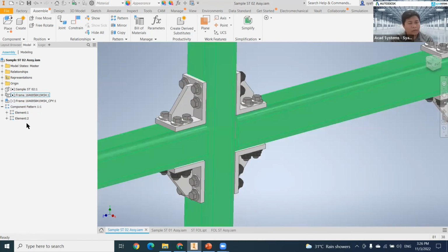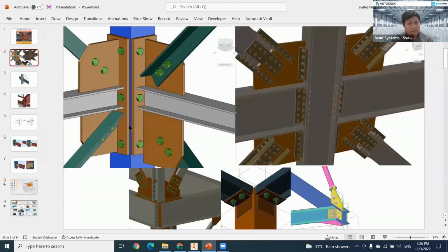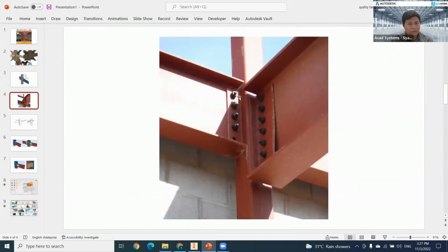If you go back to our sample here, what you can do is this: if I plan to create this kind of joining, no problem. I just need to create a plate. Make sure that all these items are trimmed with a distance for the thickness here, and then create a plate and directly do the bolt connection over here. Same goes for the others. This will be the normal concept, right? They will have a plate and another plate with a bolt connection.